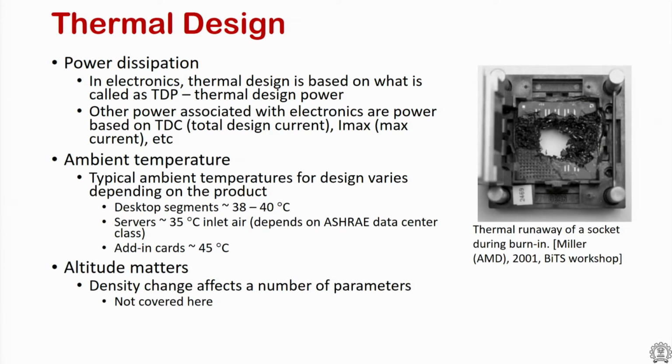But there is also something called TDC, the total design current. The TDC gives the maximum power, which happens at the beginning when you start a computer, when there is an inrush of current, and that TDC has to be managed as well if there are larger transients, but typically that is ignored. One often designs these systems for thermal design power and the ambient temperatures.